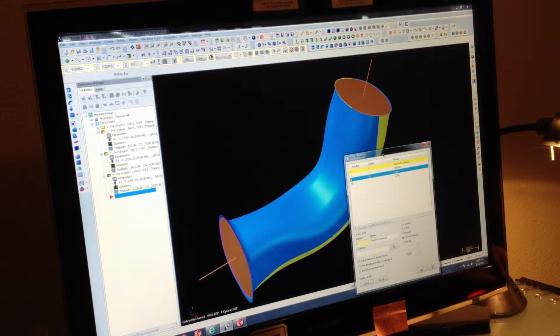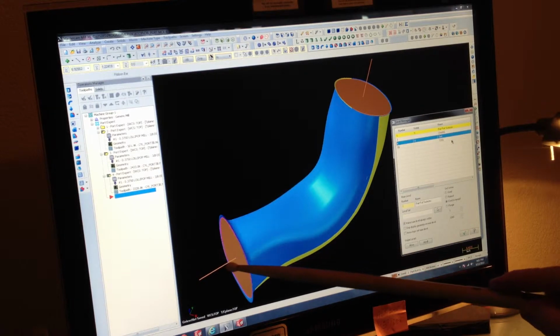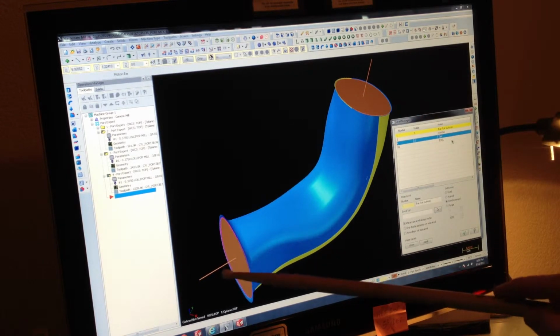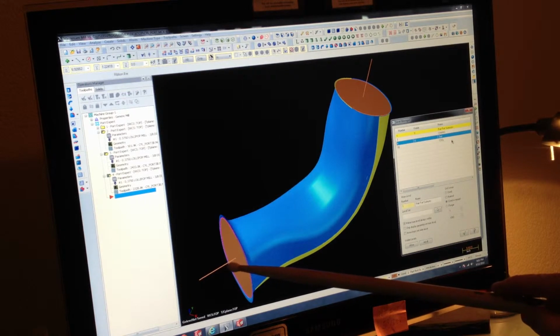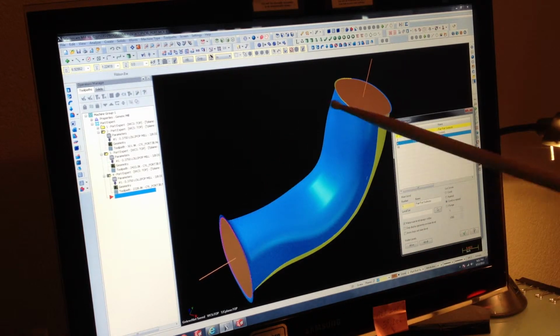So by doing that, you're giving yourself something to work with. You cannot create another surface like this surface or vector without having a curve first. So you create a curve here, and you check mark OK, gives you the curve, and then put them on a separate level. So create a level for curves, for example, and then you go back over here again on the second side of the port, and it's got to be a larger flange, and you do the same thing again. Create a curve only on one edge. You chain this around, make sure you don't miss any small lines, and then OK that. Then you have a curve on the bottom and a curve on top.